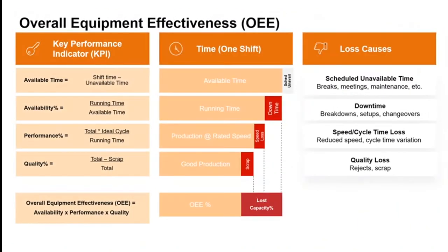So here are some of the definitions in OEE. Really, it's about these three: availability, performance, and quality. You can see the OEE calculation is availability times performance times quality, in the bottom left here. So it's really all about measuring why my machine or system is down, what's causing my downtime, why am I losing speed, and what's causing my scrap.